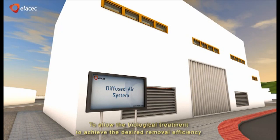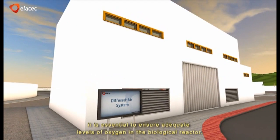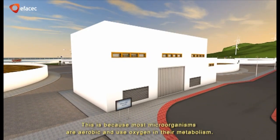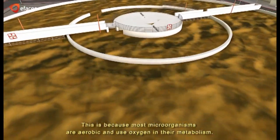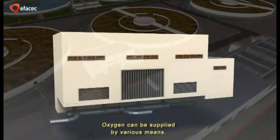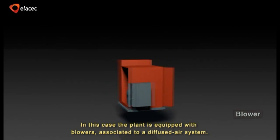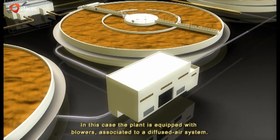To allow the biological treatment to achieve the desired removal efficiency, it is essential to ensure adequate levels of oxygen in the biological reactor. This is because most microorganisms are aerobic and use oxygen in their metabolism. Oxygen can be supplied by various means, all of which involve significant energy consumption. In this case, the plant is equipped with blowers associated to a diffused air system.